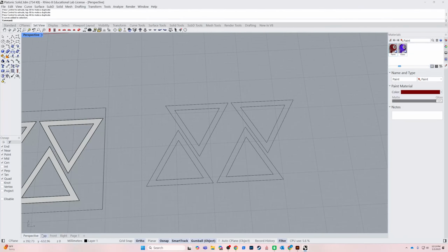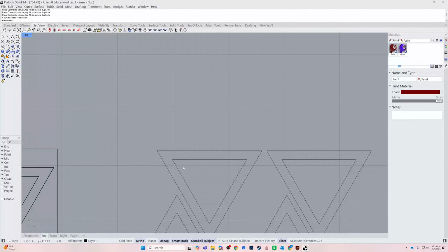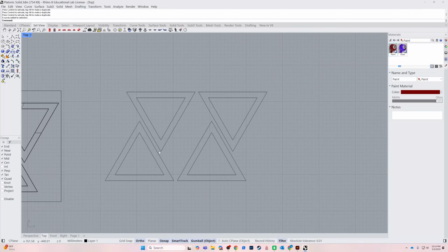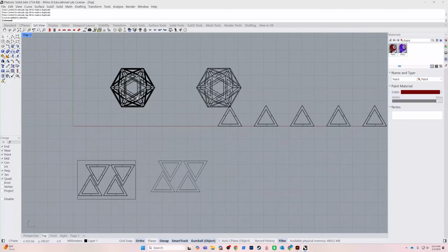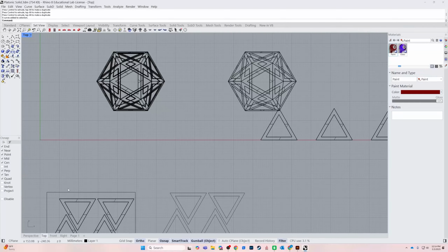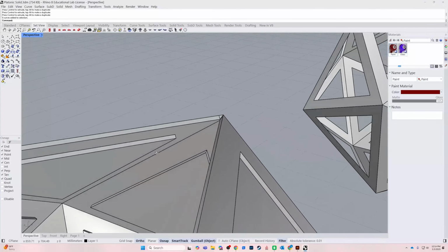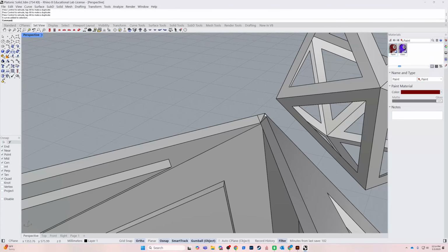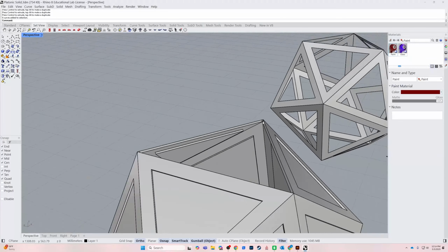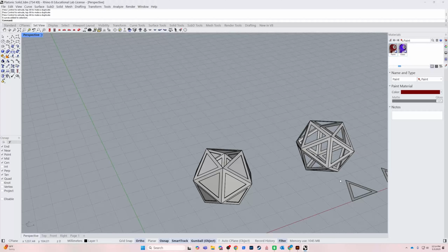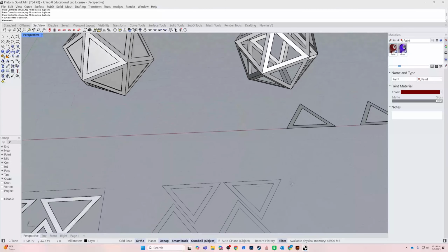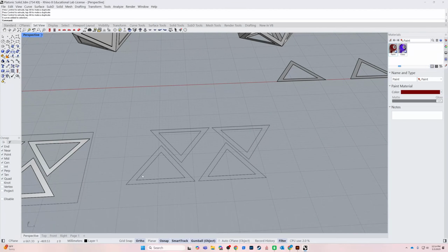Okay, other things to consider. We're going to have to create an angle on each one of these, like a beveled edge, when we're cutting the physical wood, so that when they go together, they butt up to one another perfectly the way they do in my perspective version here. You can tell that all of these are cut with an angle. We'll measure that angle in a second, but that angle needs to be cut on the bandsaw afterwards.